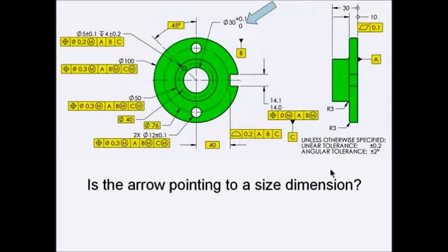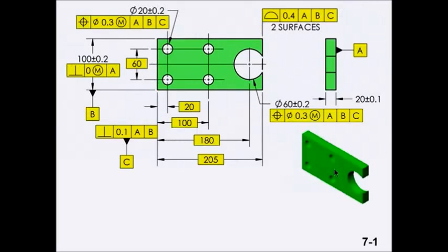The 30 is Datum Feature B, and this establishes the origin of measurement. So even though B is a feature of size, it does not require position, and its relationship to the primary datum feature would be perpendicularity. You might point out that had position been used on Datum Feature B, the result would be the same.